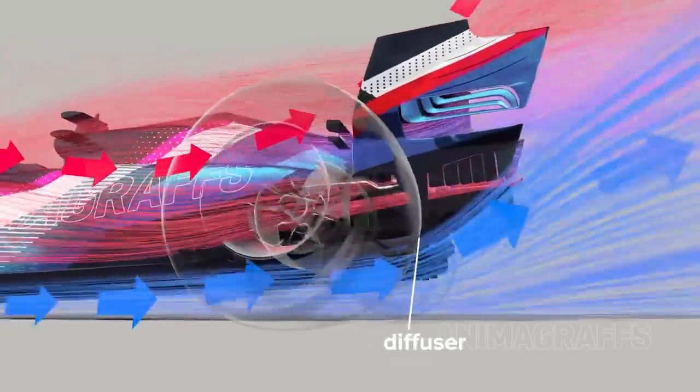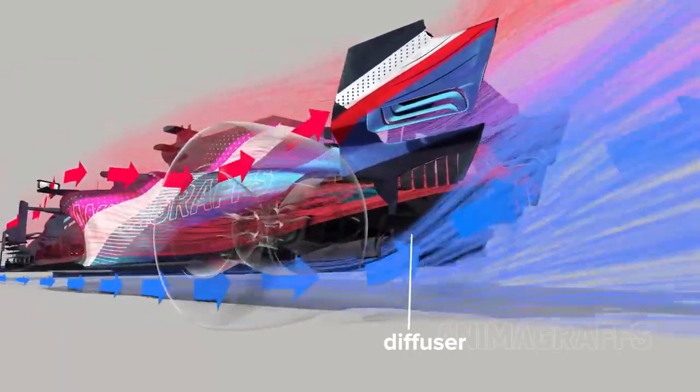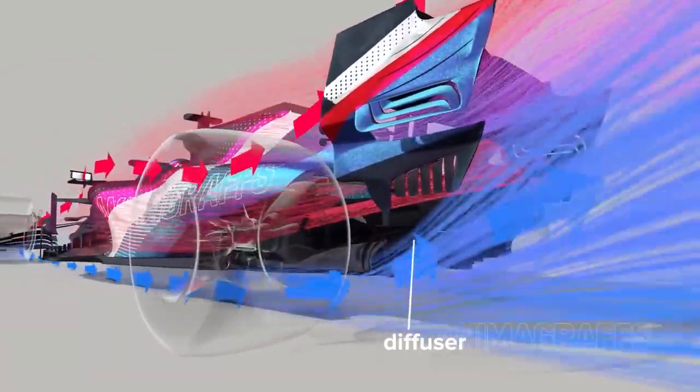A diffuser at the rear amplifies this goal, with its more pronounced upward curvature. The diffuser has vertical vanes to control and direct the massive vortices that form behind the car as air pours out from underneath.